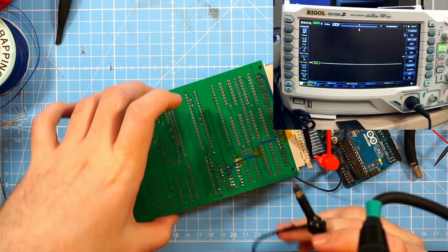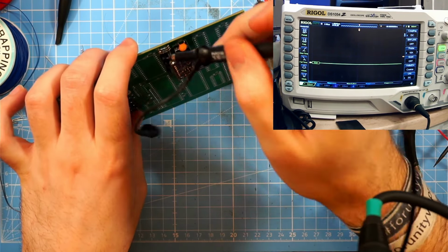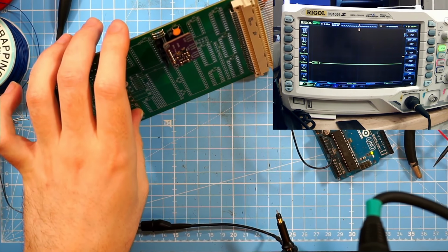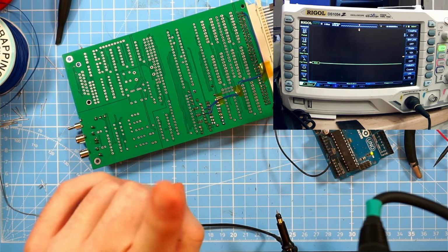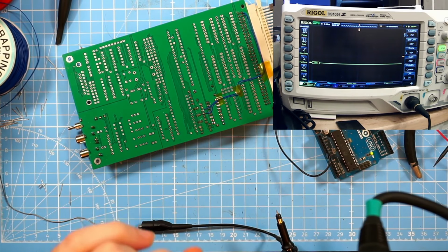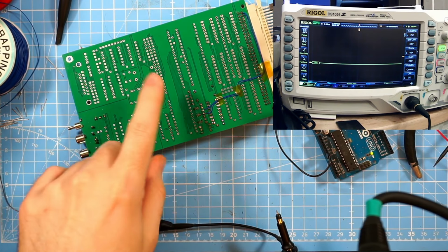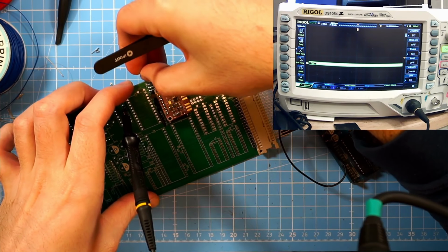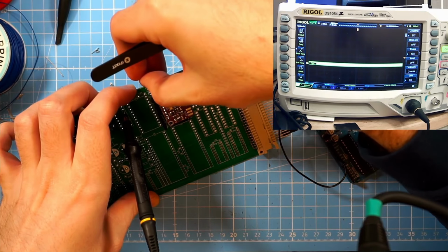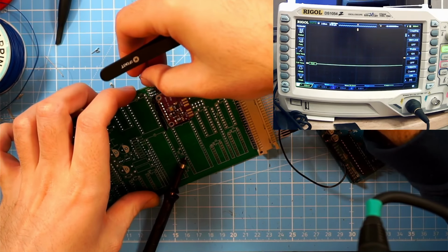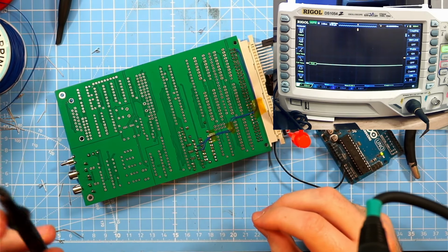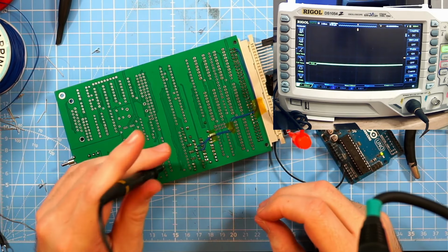You know what I'll do? I'll try to swap out the base resistor for something smaller and try again. Maybe this might be the issue, that 1K is just too much for 8 megahertz. I don't know. Let's see if this is the problem. There is something, at least. It makes some kind of difference, but not the amount that I would like to see.